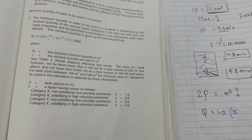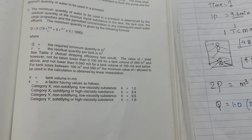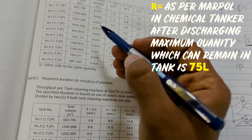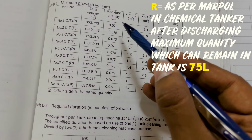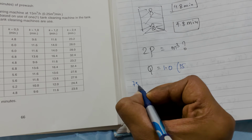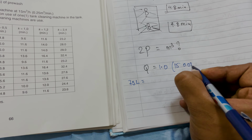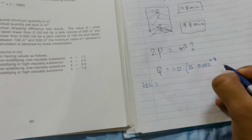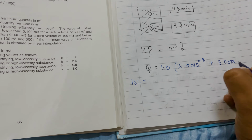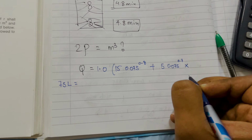So this is the quantity which will be left after discharging. Once we complete our discharging, how much quantity of residue will be remaining in that tank is this R. As per Marpol it is written that in tanks it shall not be more than 75 liters. So this is what they have written here also, residual quantity for all tanks. You can see over here it is 0.075. That is actually 75 liters as per Marpol, and in cubics it becomes 0.075 raised to the power 0.8 plus 5R. 5R is again the same 0.075 raised to the power 0.7. So we'll write 0.7 multiplied by V.